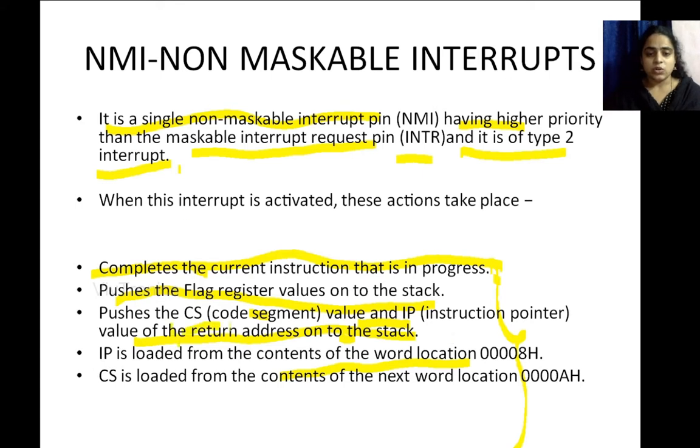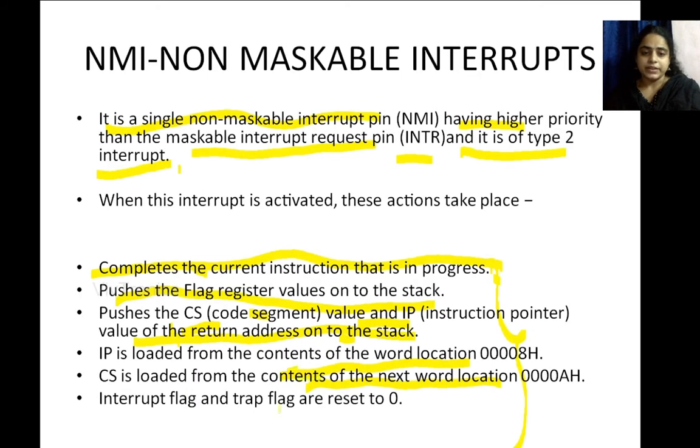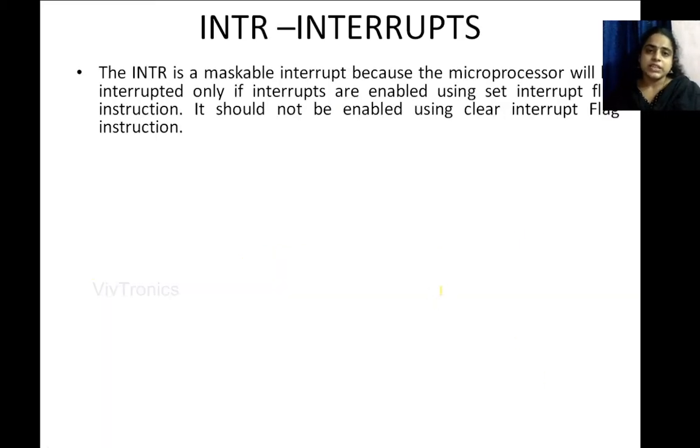Code segment is loaded from the contents of next word location, and interrupt flag and trap flag are reset to 0. So instruction pointer, code segment, flag values and everything will be affected by the NMI pin like this. And next one is interrupt.